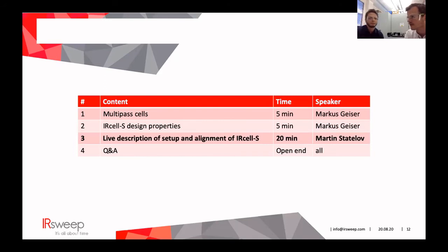Yeah, right. Of course, once you have the cell aligned, it's not easy to see anymore how many mirrors you're hitting. But if you follow with the thermal paper from the entrance aperture to the first mirror that you hit, you can clearly see, is it the second one for the full path length or another one for a lower path length, and then you know which beam pattern you have. This is also outlined in the manual.